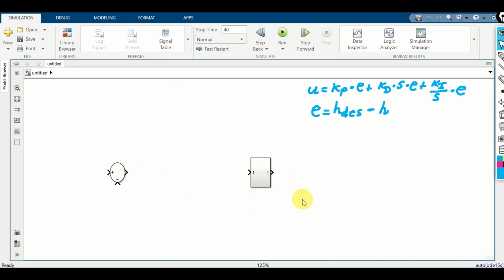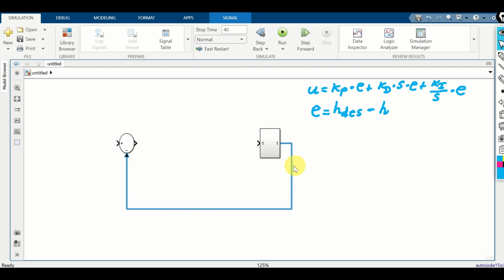Good. Let's continue. The output of our nonlinear dynamics is actually H. And over here, we assume that there is an ideal sensor measuring the tank level. That is the liquid level inside of the tank. Since the sensor is completely ideal, we don't model the sensor. That is, the sensor is simple constant equal to 1.